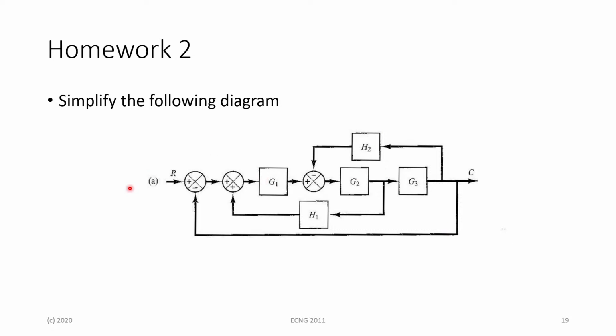And your second homework would be to attempt to simplify the following block diagram. Like I said, the trick behind this is that you want to keep finding feedback systems or feed forward systems to reduce, such that you can eliminate these summation junctions. A good idea of how we can start approaching this problem: if we watch this takeoff point in between G2 and G3, mapping H1 here, we can see that if we move it from this point to the right of G3, and put it all the way across here, G2, G3, and H2 represent a negative feedback system which can be immediately reduced.